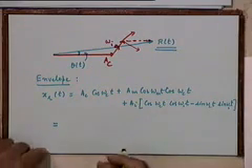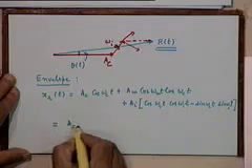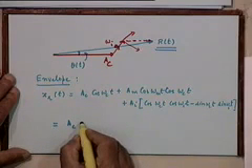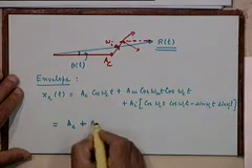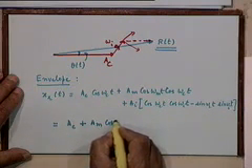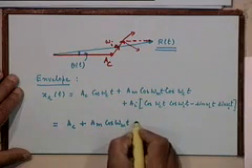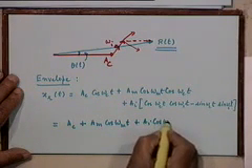If I have it in the quadrature form, I can easily identify the nature of the envelope by taking the square root of the modulus of the thing, right? So what is the in phase part? It will be AC plus AM cosine omega CT, cosine omega MT plus AI cosine omega IT.